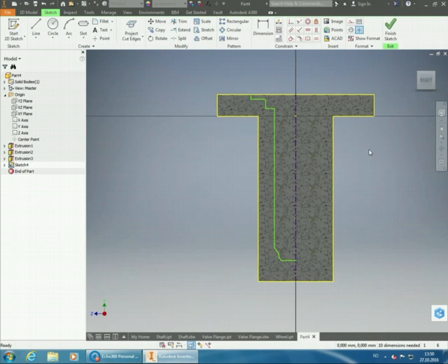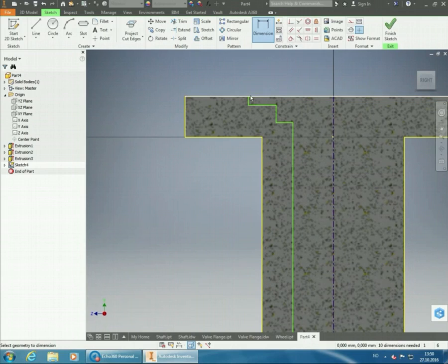So now I'm going to start putting in the dimensions for this. I'll start off by putting in the diameter dimensions, just so that we get a feeling for the width of this one. So I'll start up top here. And here you can see when I have a center line instead of a construction line, it automatically chooses a diameter. I don't have to right click and do linear diameter for it, which should have tipped me off in the first part we created.